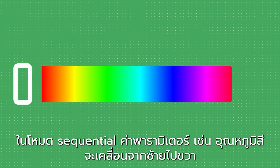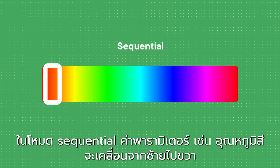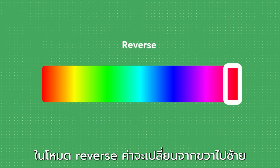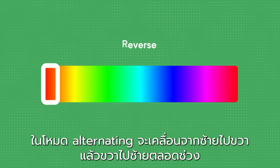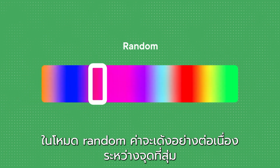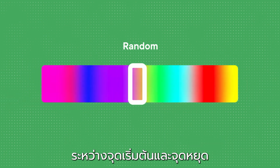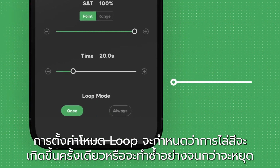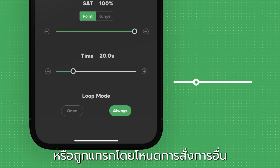In sequential mode, the parameter value, such as color temperature, will move from left to right. In reverse mode, the value will shift from right to left. In alternating mode, the value will move left to right, then back to left throughout the range. And in random mode, the value will constantly bounce between random points between the start and stop points. The loop mode setting will determine if this chase will occur once or if it will repeat indefinitely, until paused or interrupted by another action node.